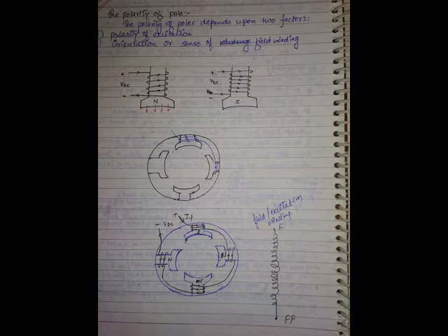Now listen. Let us take the armature core as a solid cylindrical drum. What is the purpose of the armature? Basically, to hold the armature conductors. So it is slotted. In these slots, armature conductors are placed. The armature is mounted on a shaft, which means inside there is a shaft coming out. So you will connect a motor and rotate the armature.